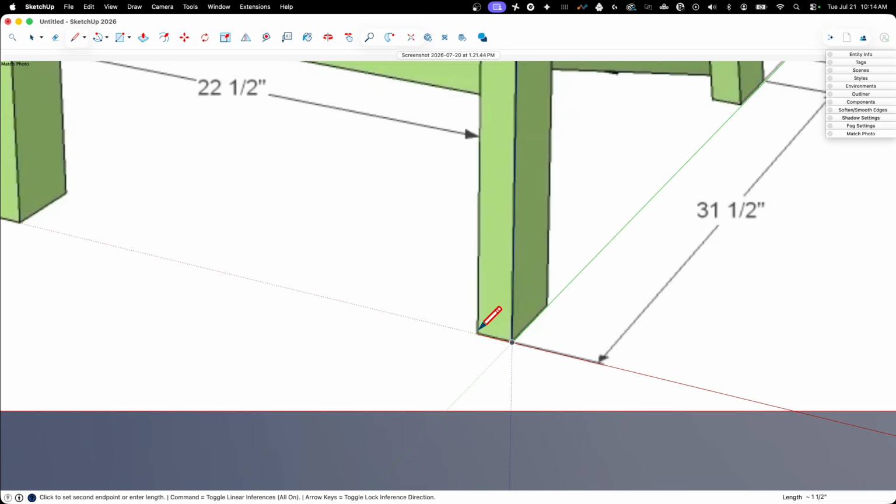So I'm going to go this way, 1.5, enter. I'm going to come this way and come back right here. That should be around 3.5. Yep, 3.5. I'm not clicking. I'm typing the number in that I want to go across because I don't want it to round. So this time I'm going to come back across the red axis. If I hold down Shift while I'm on the red axis and move towards this first axis, it'll snap to 1.5. And I'll click here, close that up.